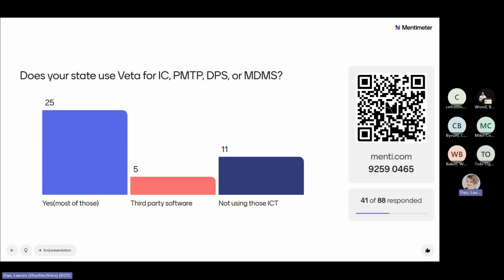We've seen a lot of these technologies in different examples. Curt showed one earlier, and we're looking at pass count mapping and thermal behind the paver. Very seldom, in my experience, is there one thing causing a major problem in the field. If I was just skipping one roller pass, but I had uniform temperatures and the right material on the paver and all that good stuff, I'd probably still have good density.